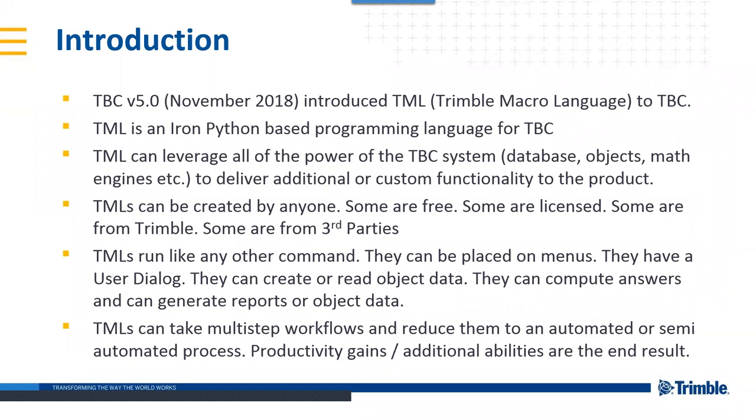Anyway, TML is something that you can use that basically can write programs that have user interface, can create icons that sit on menus, that can have help systems associated with them. And TML can access all of the functions of the Trimble database. So you can ask questions of the database, you can query and select objects, you can run mathematics calculations using the TBC math engines for geometry calculations, etc., and use that to deliver additional functions or additional objects or additional workflows or additional reports or whatever you might want to the software.